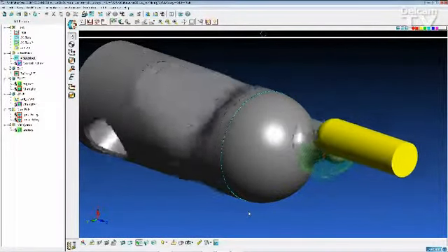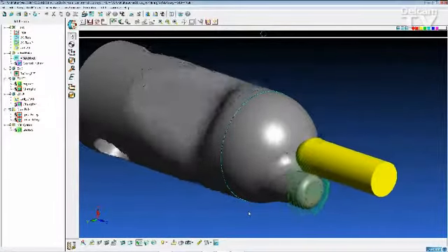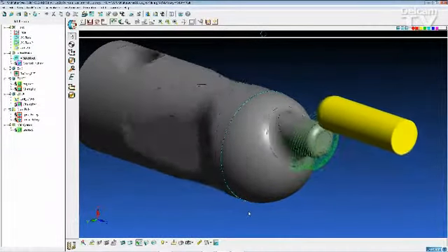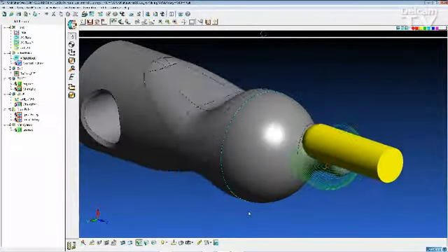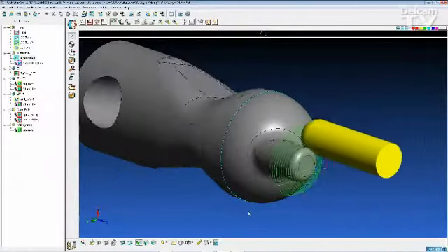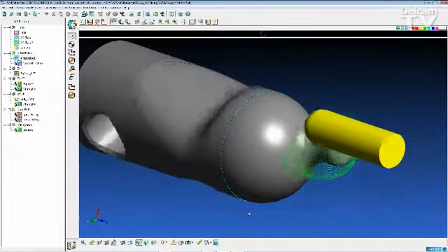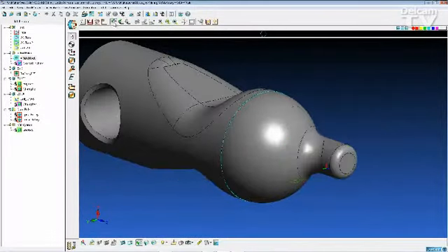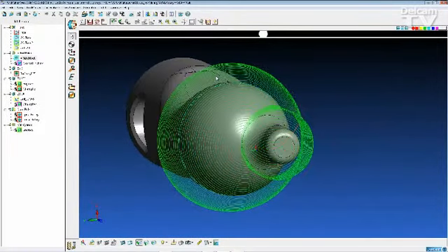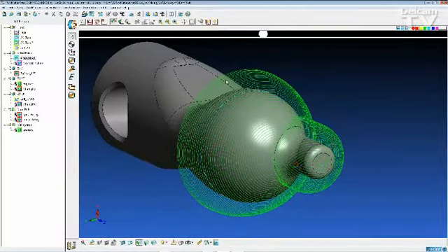So beyond being able to just use different types of strategies, you can generate different types of motion. So here we're machining using a rotational axis, the tool oriented at the end of the part, doing 3D offset machining. So you can see it's offsetting a pattern going around the part, but it's using the C axis of the machine tool to do so.